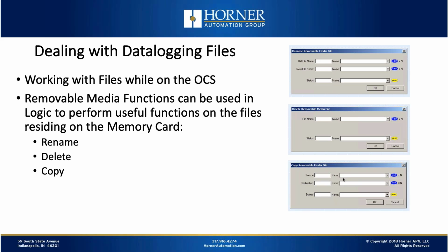So that's kind of the equivalent of the old SneakerNet manual way of grabbing files off of the OCS, by basically having someone walk up, plug in a USB drive to the outside of the enclosure through an extension cable, and then have them press a button on the unit, which triggers a copy function, which would then copy a complete directory of files, for instance, from the microSD card over to the USB drive. So that's definitely another capability that's there when you're talking about dealing with the data logging file.